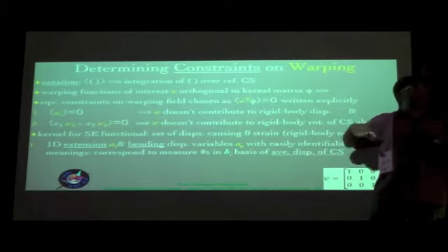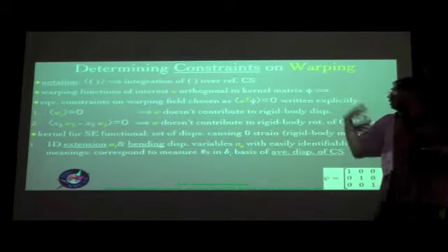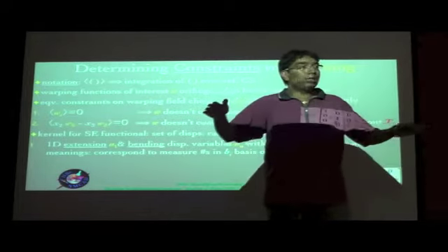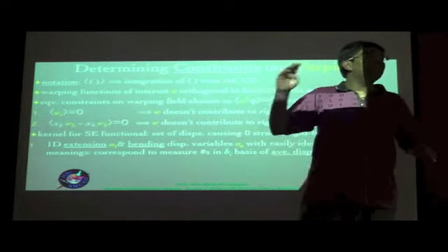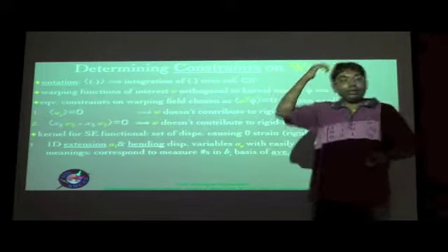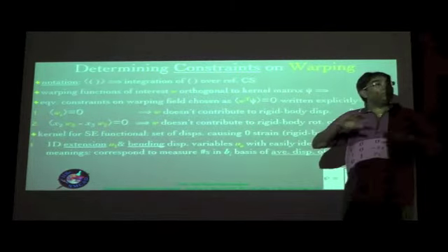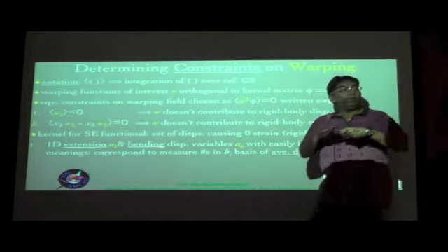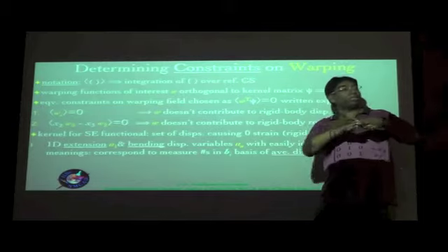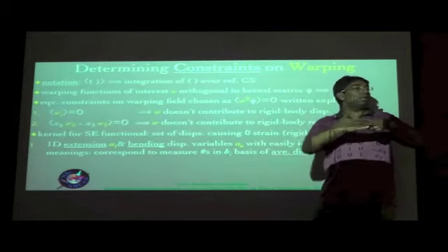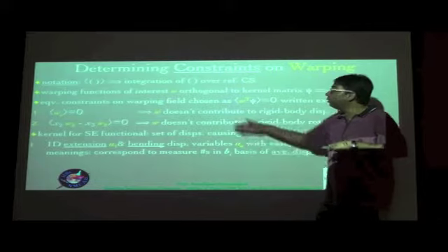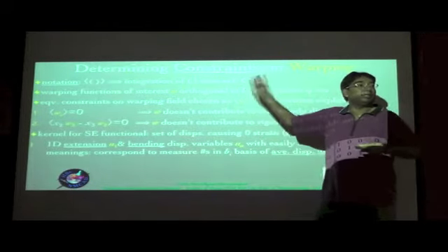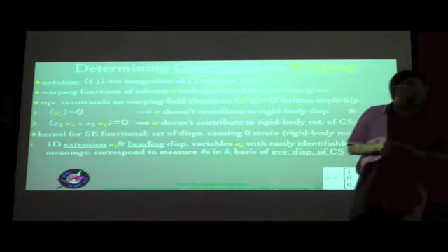But even in a situation where transverse shear is not important, recollect that we have only 4 orders of redundancy, because instead of 3 quantities we have introduced 7. So only 4 constraints are in place, and those are the 4 constraints which are resulting over here. In other words, even in the most general case, in some way the 2 displacements U2 and U3 would be related to those rotations which are taking place about x2 and x3. So that is the reason why you don't get 6 constraints but only 4 constraints. The other reason, of course, is that the order of redundancy is 4 and therefore only 4 constraints are there.